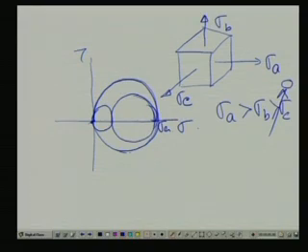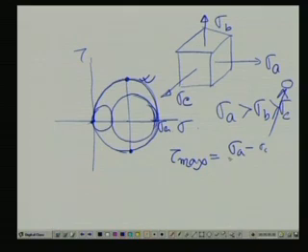Now, as per the criteria, at this position for the outermost circle, what is the value of this tau max? This tau max is nothing but the radius of the Mohr circle. So, tau max equals sigma A minus sigma C by 2, and now I write sigma C as 0, that means it is just coming out to be sigma A by 2.